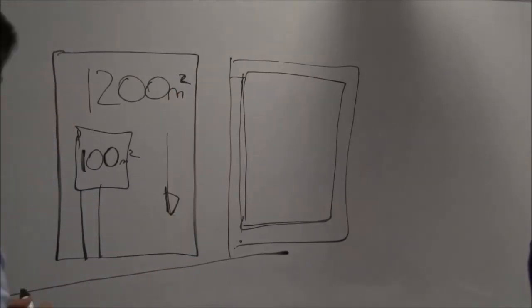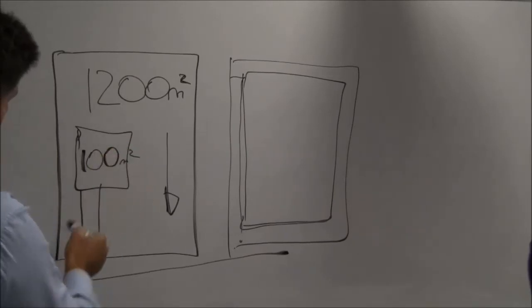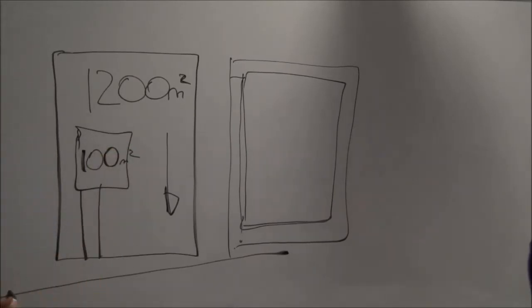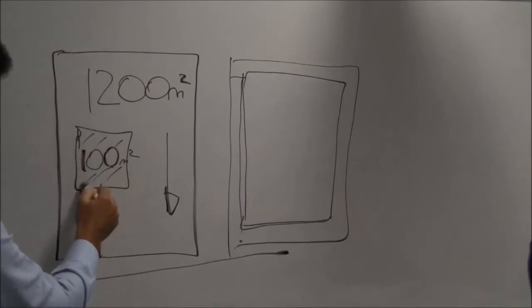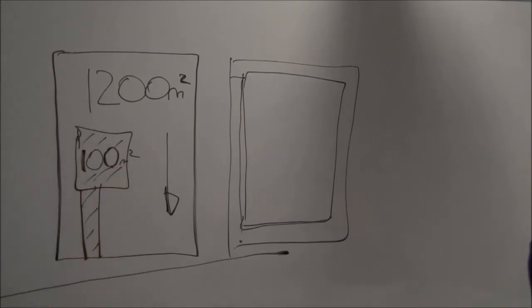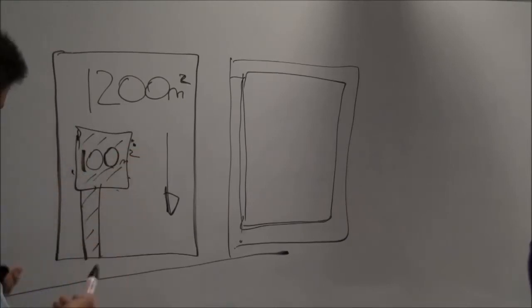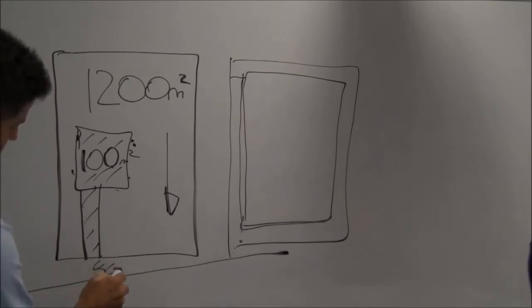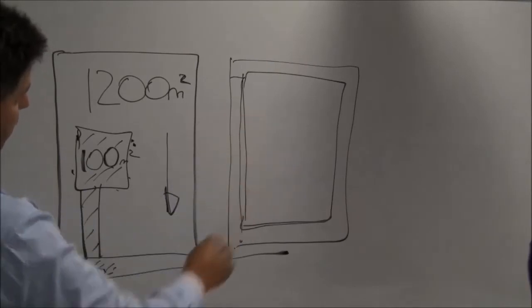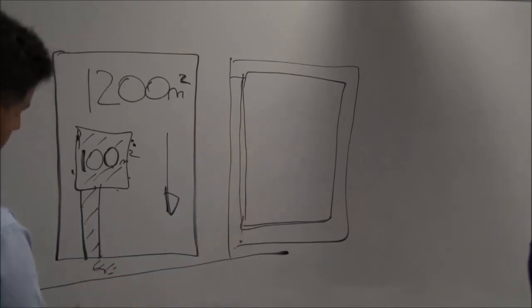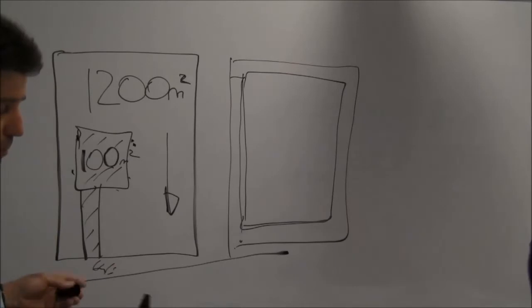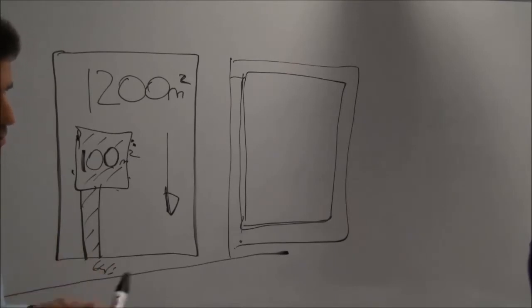Obviously we have a small percentage that is the fraction of impervious area over the overall site, so the hard runoff. It'll have all the downpipes and everything else, and it may have a flow of, I don't know, 6 litres a second coming off the site. Once our developer comes on who wants to develop the site, we still have to maintain maybe that 6 litres a second, or council might say you're limited to whatever the flow rate may be.